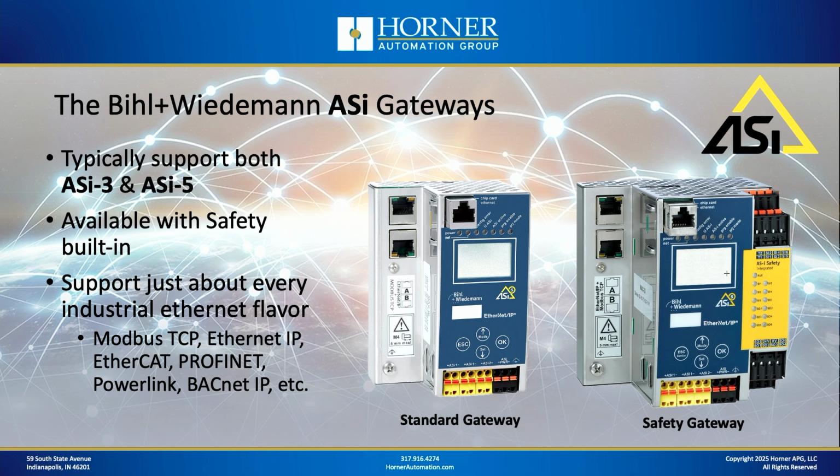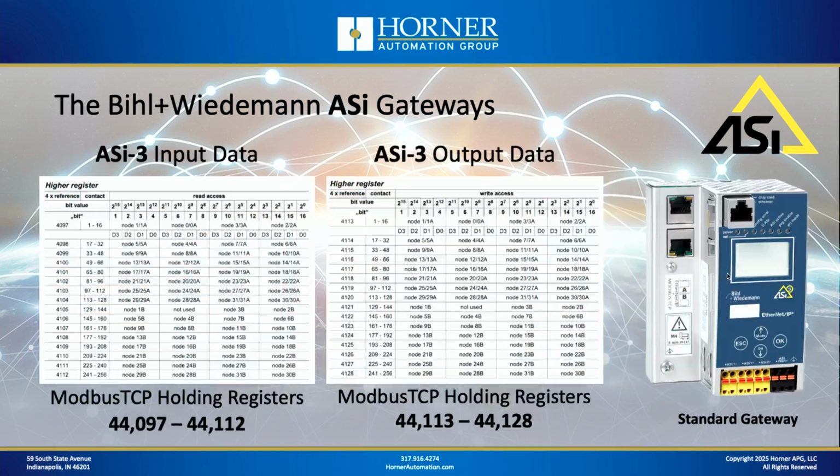Now, they provided not only the ASi devices, but also the gateways, and they offer gateways with and without safety built in, and they also support just about every industrial Ethernet flavor you can imagine. And again, for our demonstration today, I'm using Modbus TCP because that's the easiest way to interface with the Horner OCS all-in-one controller.